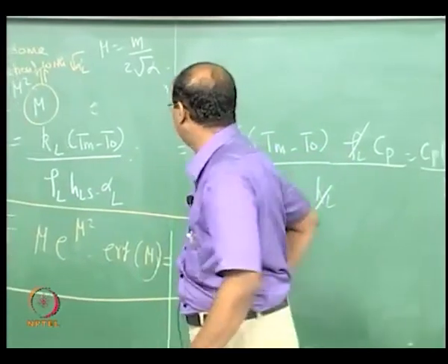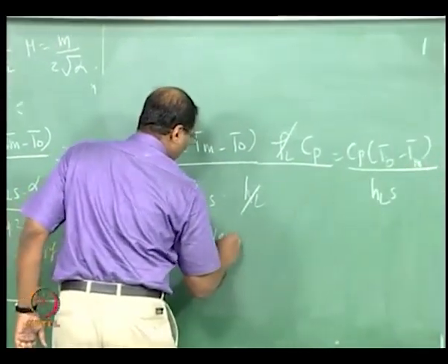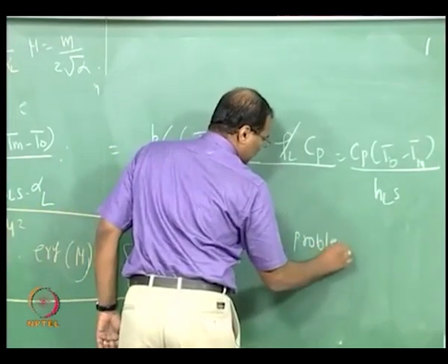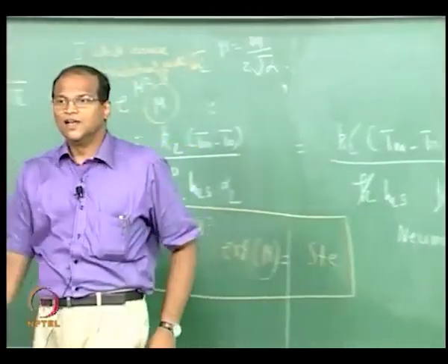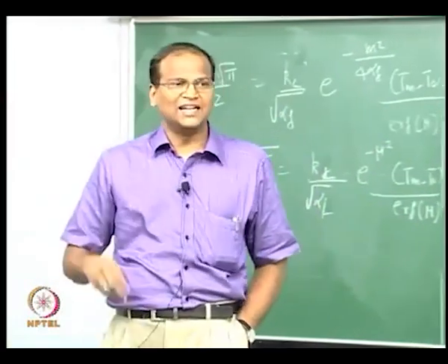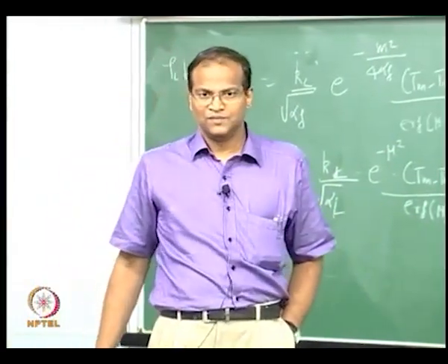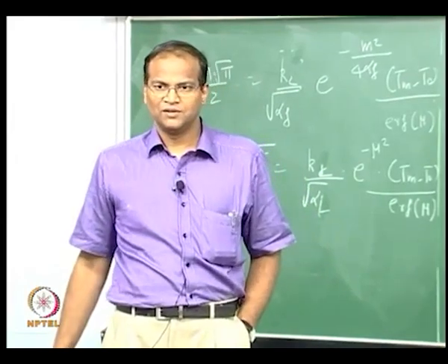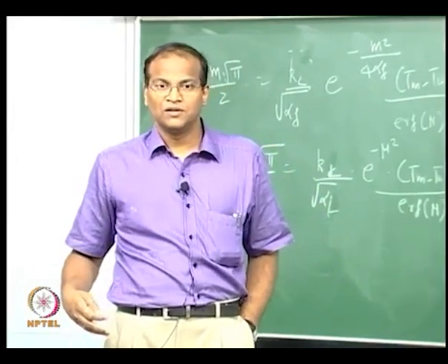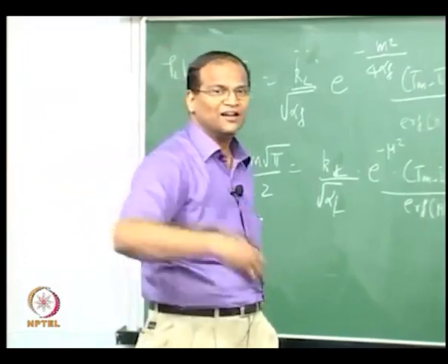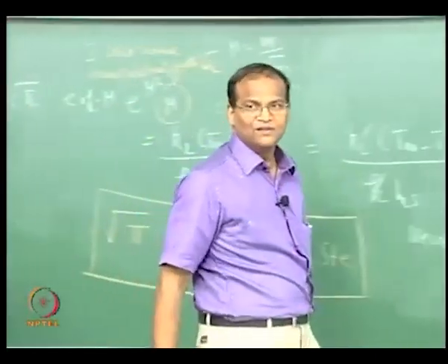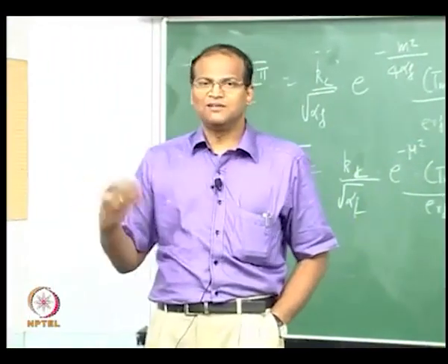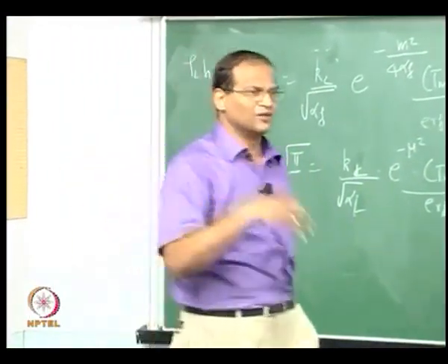What is the Neumann problem? In the Neumann problem, the Ti is less than Tm. Initially the body is at a temperature lower than Tm, everywhere it is at Ti. There will also be sensible heat, and you will have to consider conduction in both the liquid phase and the solid phase.